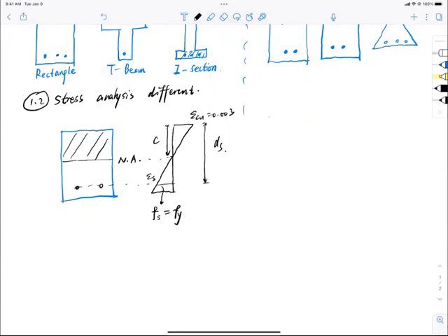And now if you look at the stress, then use my Whitney stress block. So I have a right here, that's the effective compressive zone. And my total concrete compression is Cc right here, and this is half of a distance away from the top. And now this magnitude right here, 0.85 f prime c. And I know that my tensile force right here equals As Fy. Okay, so that is the regular section, right?